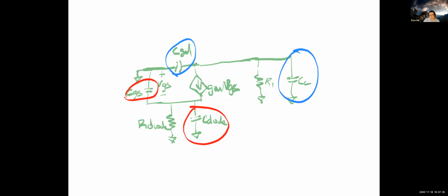Now the next question is, can we just eyeball this? Can we simply write out, without having to derive any expressions, what the time constants are? And the answer is no. For all of these cases, the fact that we have this R diode down here is going to complicate our KCL and KVL expressions, and we can't just directly identify what the driving impedance is.